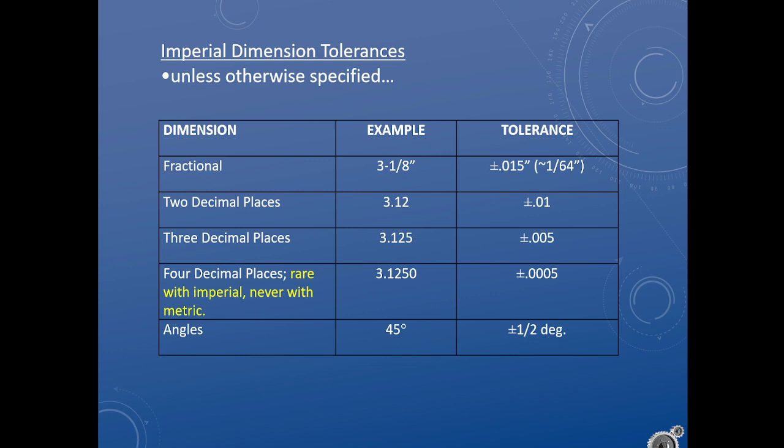Yeah? You gave the example that the range would be from 3.11 to 3.13. Is that range inclusive? Typically inclusive. But you would have to shy on the low side, so often we would throw out something that actually hit that threshold, because then we have the precision of our tool measuring it. Error in that side, we might go, I'm not actually sure it's within spec. Oh, spec means specification. Within specification means as defined, as required. Angles usually plus minus half degree.